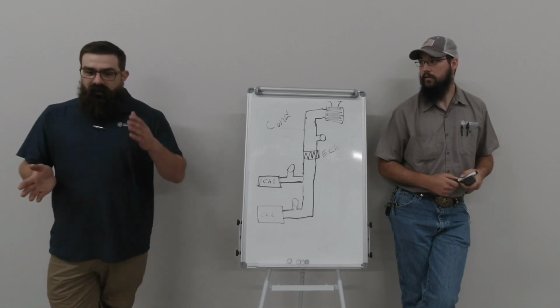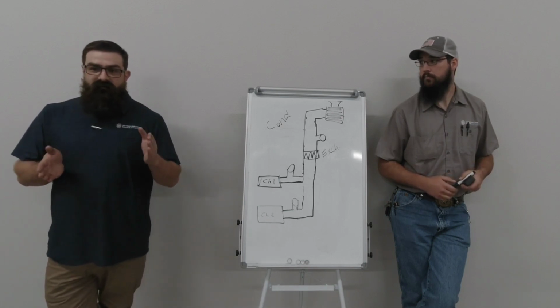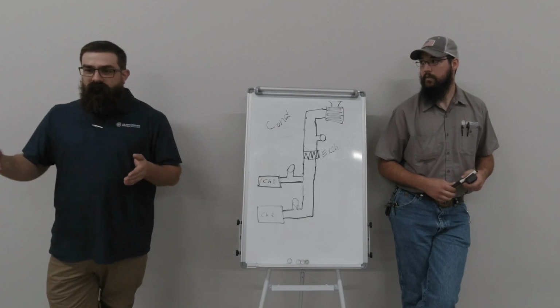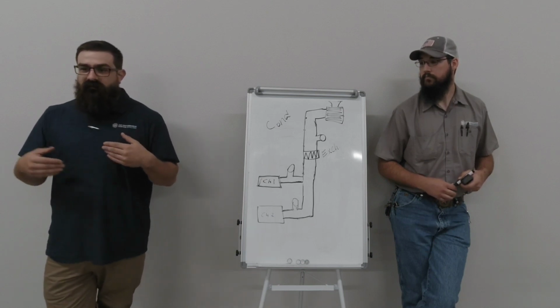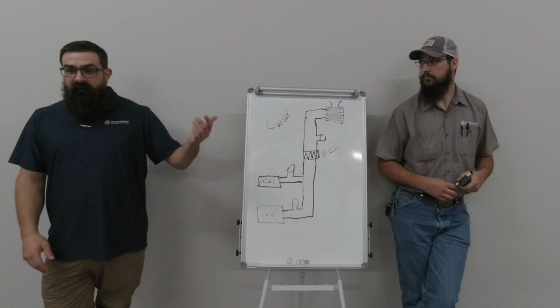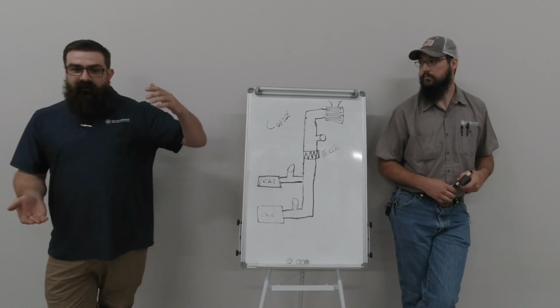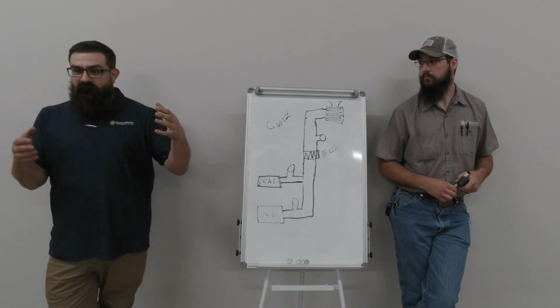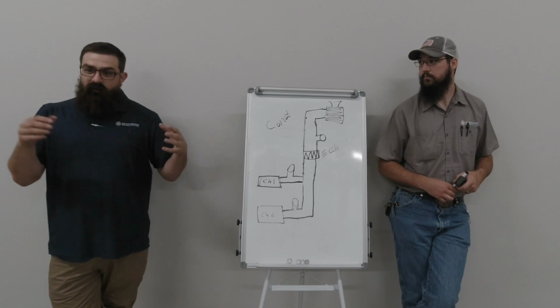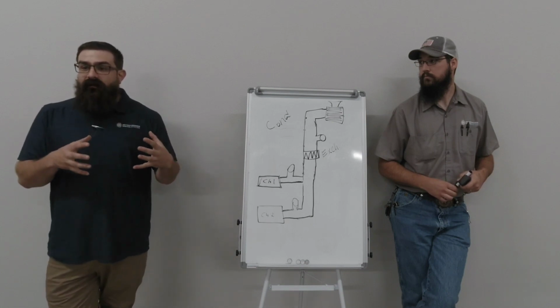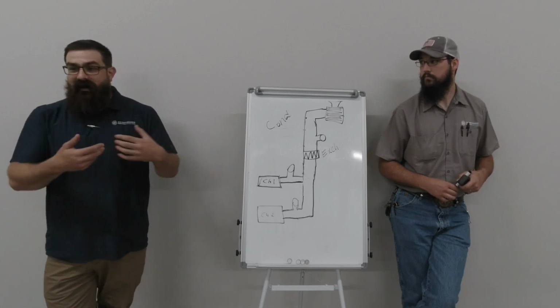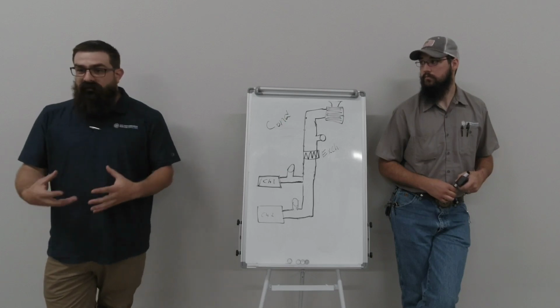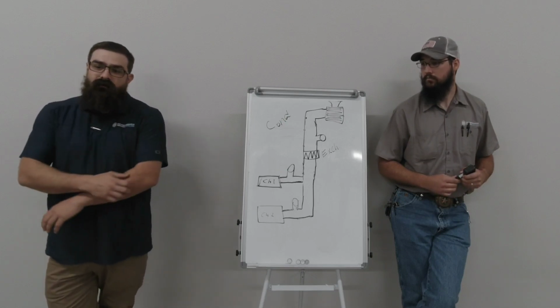So flow and temperature are always directly related. Too much flow, you won't draw any temperature out. Too little flow, you'll draw a lot. That's why we're saying 80 entering and 100-something coming out. That water spends so much time in that coil, it's gaining a lot of heat. You're not necessarily drawing a lot out of the object, but the water is picking up a bunch of heat because it's sitting in there so long.